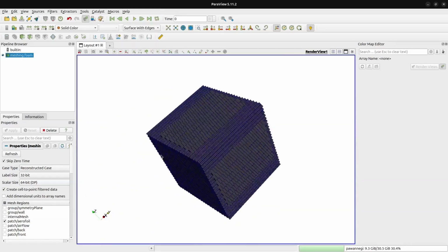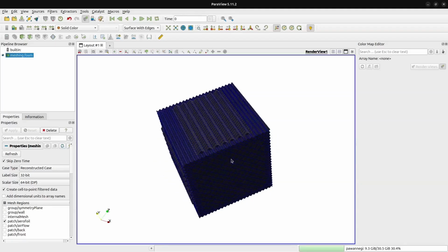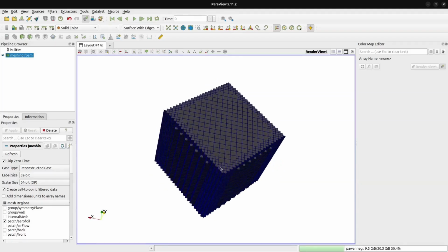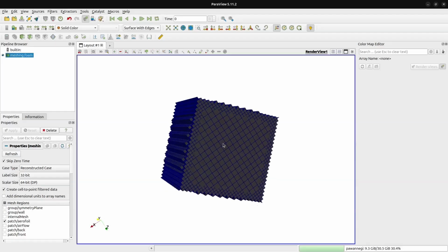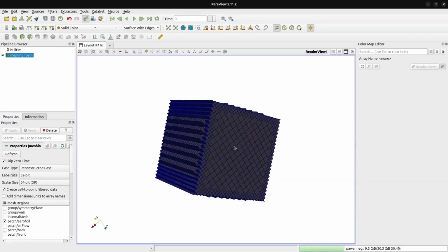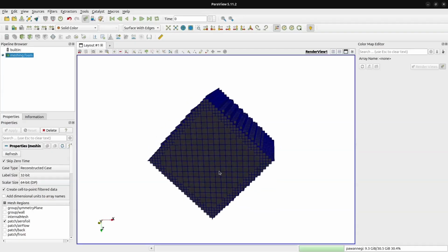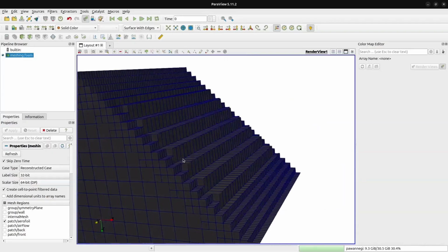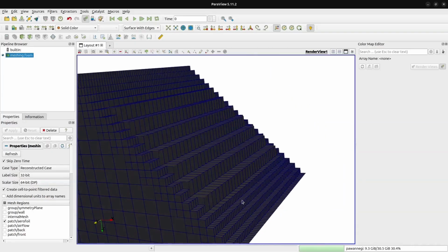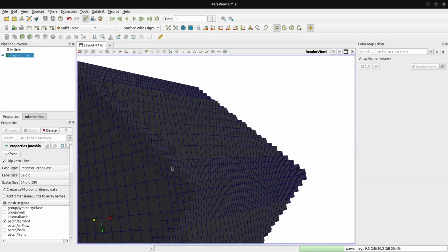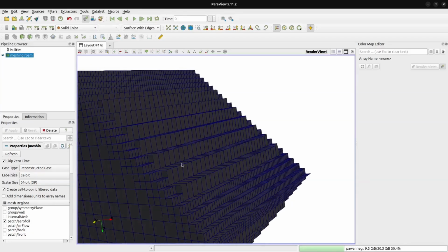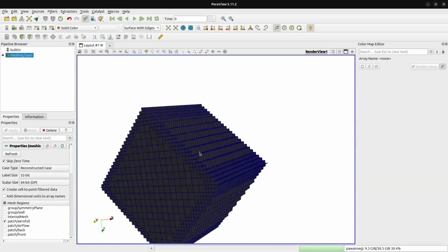And if you look at the surface mesh, then you can see that it has created a very good mesh on some of the surfaces which were aligned to the Cartesian grid, but since they were not aligned, in the castellation stage, it just created the requested mesh size on the regions that we have selected. For example, we said that near the feature this should be the mesh size, and on the surface this should be the mesh size, and so on.